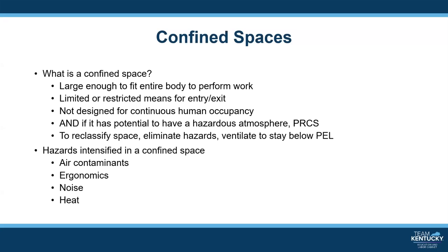One means of ventilating the space in a confined space is to use spot extraction. For example, through exhaust fans or hoods near the welding site, which are exhausted to outside of the confined space area. If spot extraction is not possible at all, then ventilating the entire space is an option. Companies should thereby select an air supply and exhaust solution to ensure a continuous flow of air. The supply and exhaust must be at different locations.